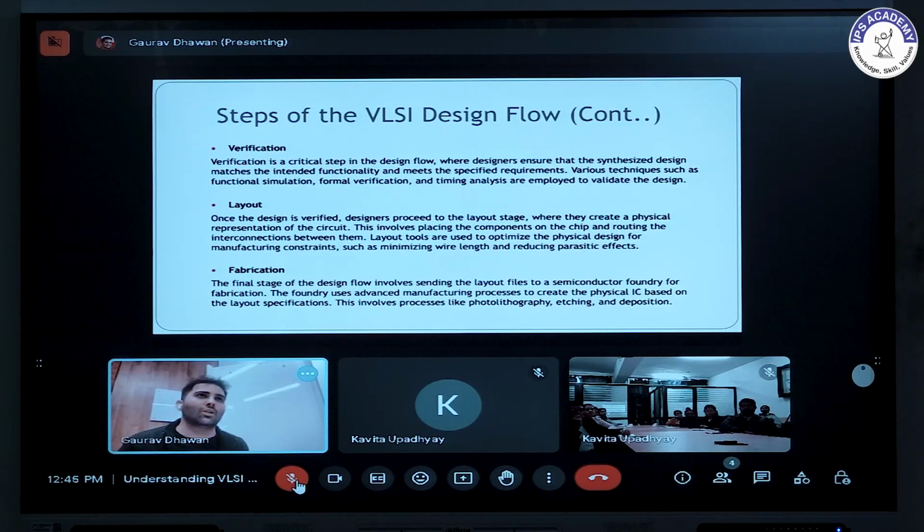Timing analysis will be done. So timing analysis is something like, let's say this is a chain of inverters going to a flop. This is a clock. Let's say this is your design. This is a delay of 1 nanosecond. This is a delay of 1 nanosecond. And since this is a clock pin and this is a Q pin, the delay of this flop is let's say 10 nanosecond. So for input A to pin Q, the A to Q delay is 1 plus 1 plus 10, that is 12 nanosecond.